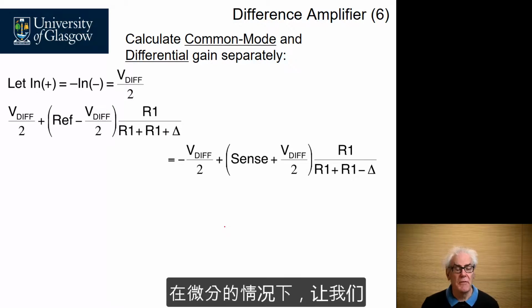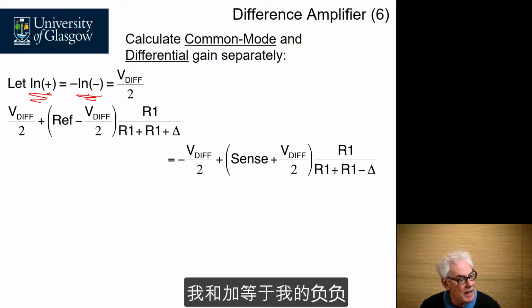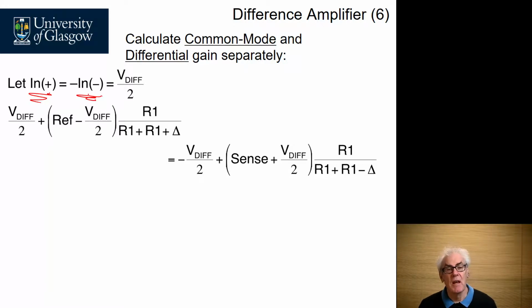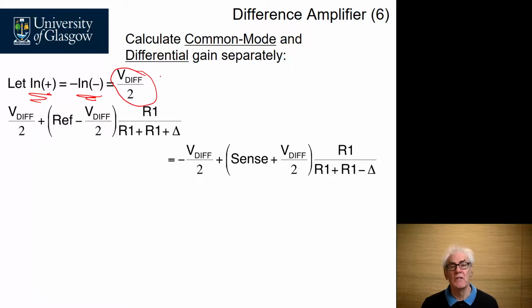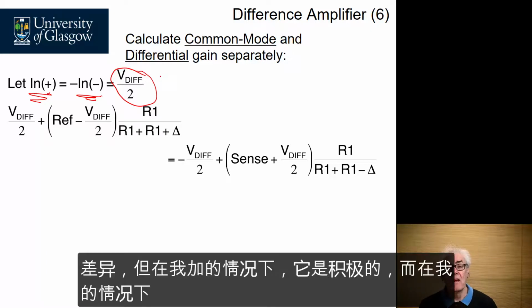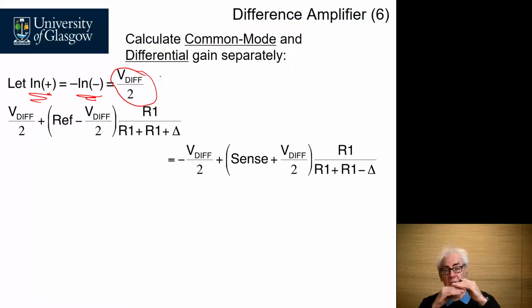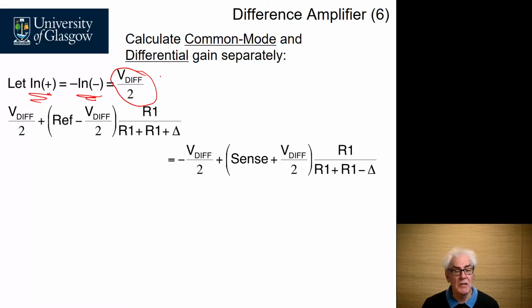In the case of the differential one, let's let In plus equal the negative of In minus, and we'll call this the difference voltage divided by 2. In other words, the full input voltage is Vdiff, but In plus is going positive and In minus is going negative. Doing the analysis in the same fashion as before, we land up with the two equations here.